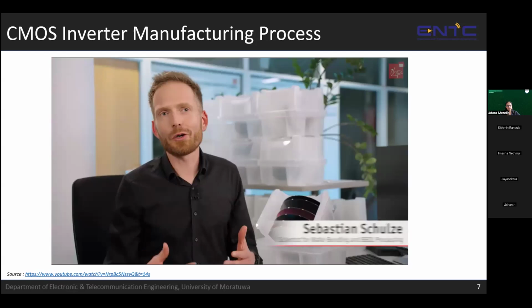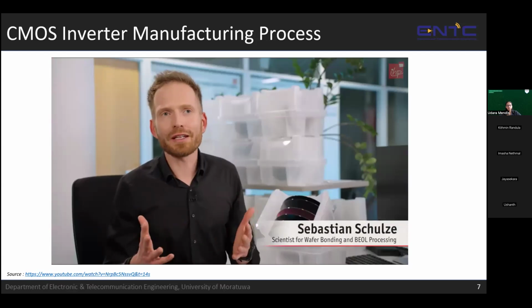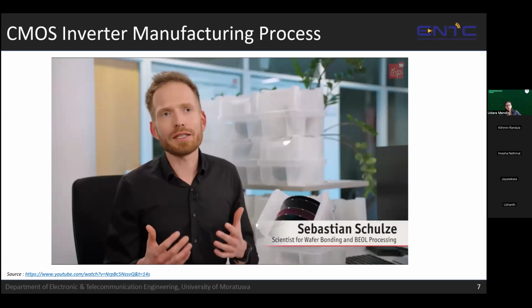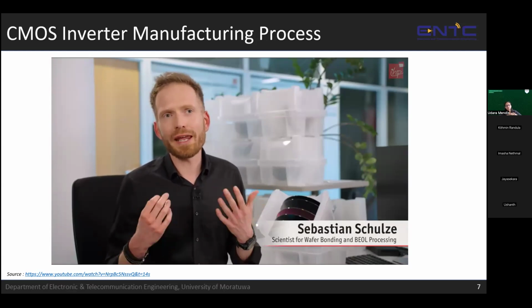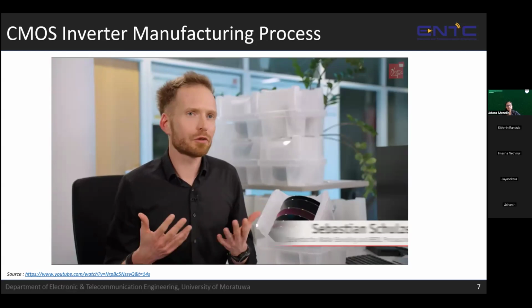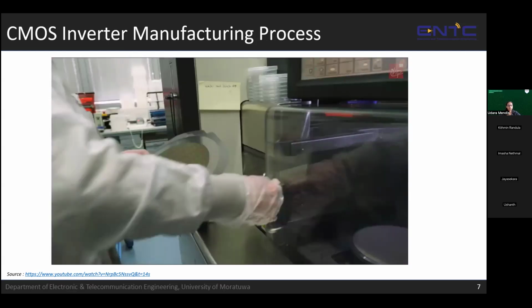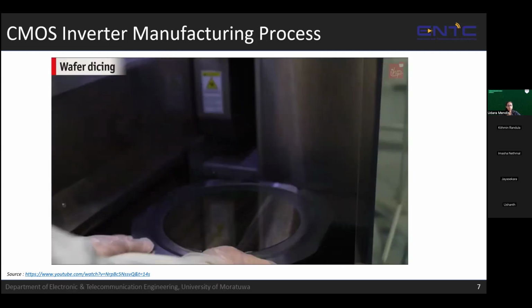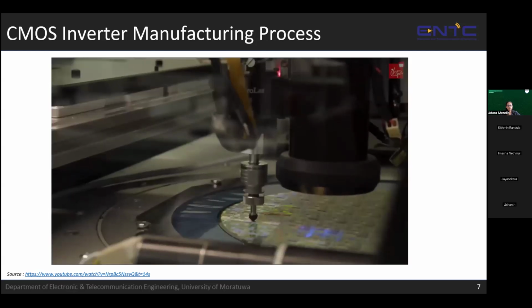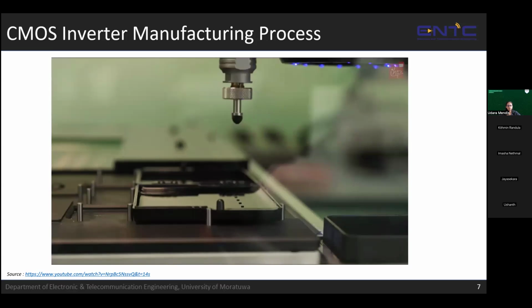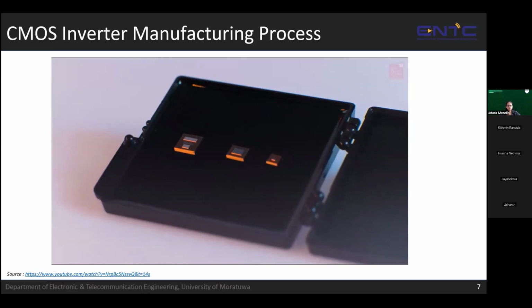The processes shown are repeated over and over again to produce our complete integrated circuit. We need over 600 steps for the entire production, which takes about 3 to 6 months. Each wafer is then cut into many small pieces called dies. Dies and related circuitry are chips that make up our modern electronic devices.